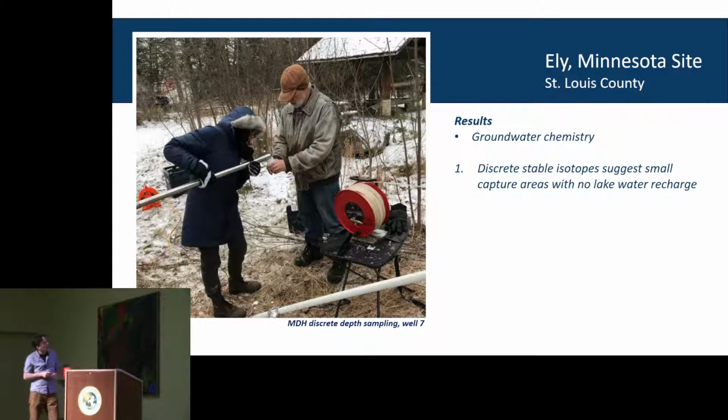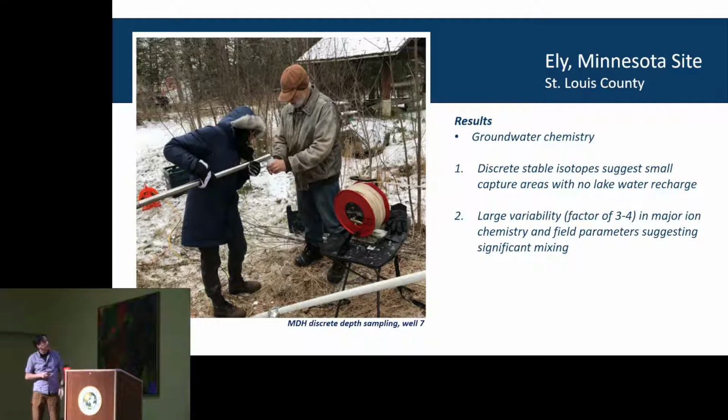So we did do a number of different groundwater chemistry techniques. The stable isotopes that I showed you earlier, I highlighted that little orange set of wells, and those wells were nowhere on the evaporative trend. So we don't feel that the lake is influencing them at all. There was no evaporative signature in the groundwater wells, even though they're in very close proximity to the lake.